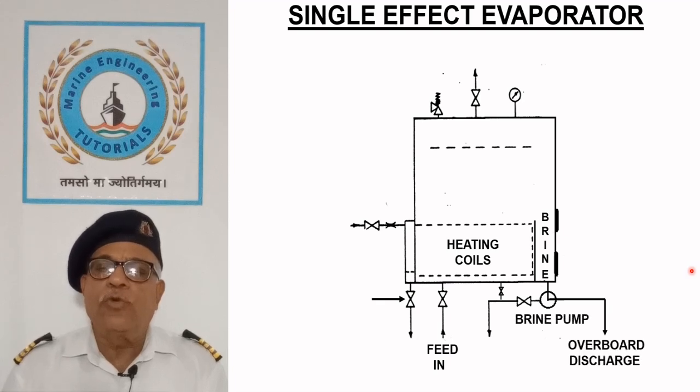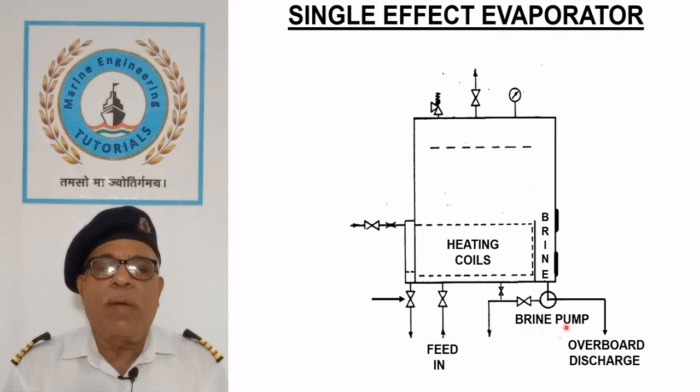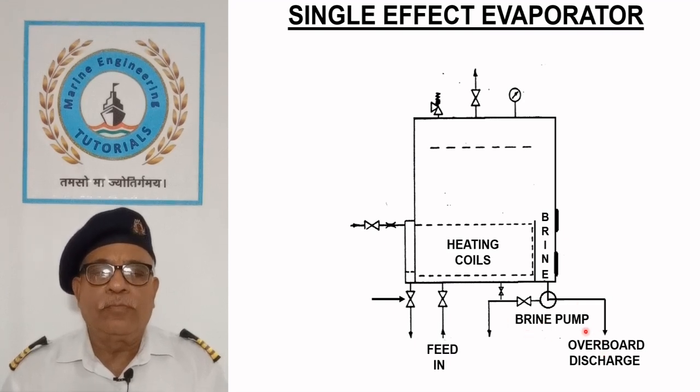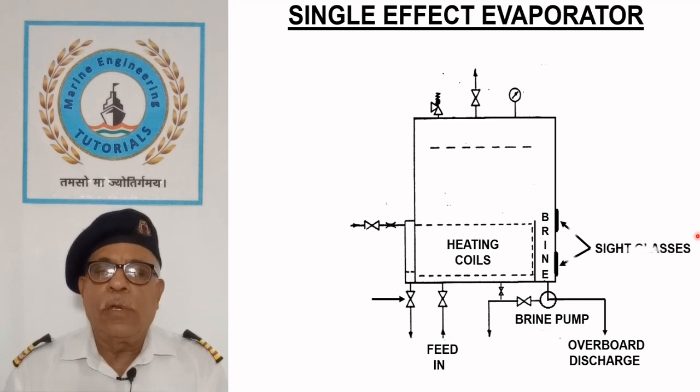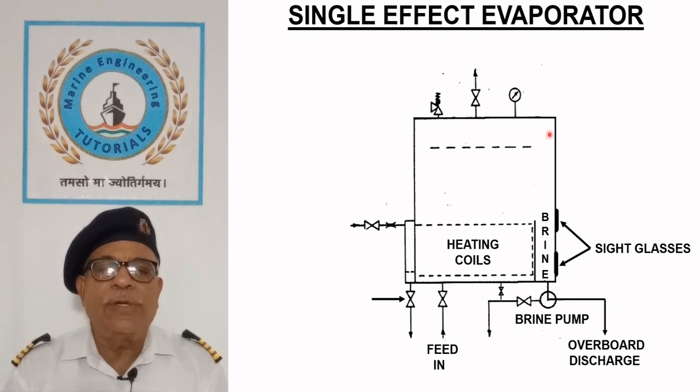Brine was continuously discharged overboard through the brine pump. Side glasses were provided to monitor the brine level in the evaporator shell.